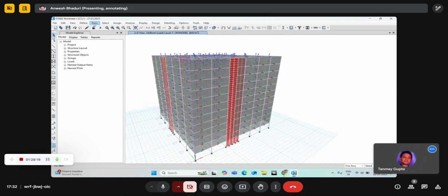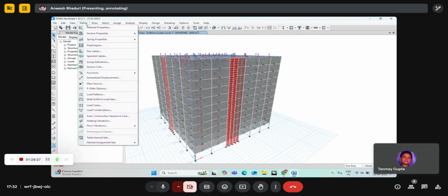Your automatic load combinations for design will cater to your wind load analysis. Only for your seismic, we need to have some user load combinations. For automatic combination, will it take both wind and earthquake? We generally do for one.